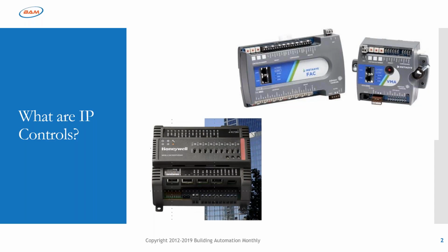When integrating field devices, such as fire alarms, chillers, etc., what are the most important parameters of BACnet IP? Well, one, that they support BACnet IP. I don't mean that to sound sarcastic. I hope it doesn't. There's just a lot of stuff that says it's BACnet IP, but when you actually get into it, it doesn't really support it. So that's number one. Number two is making sure that you understand your device instances and device object IDs.